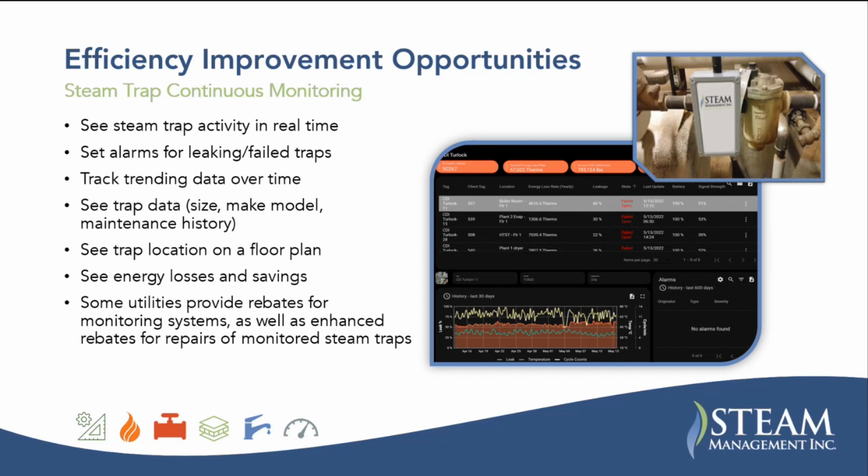I know the example you're showing is a cellular backhaul using a LoRaWAN network, but for instance, Armstrong uses Wi-Fi. So Wi-Fi or cellular backhaul are the two. Okay. And the Wi-Fi would be an independent network, so you wouldn't have to go through a firewall. You basically have to create your own independent Wi-Fi network that communicates independently of the IT infrastructure of a facility.